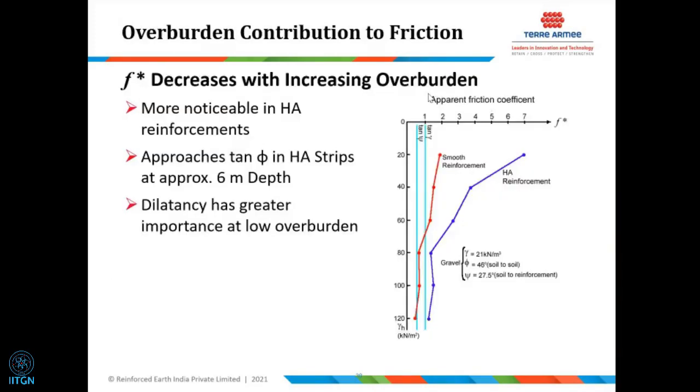And generally, the coefficient of friction depends on different kinds of soils. With a high coefficient of uniformity soil, with more gravels, you can get a much higher coefficient of friction. And with a silty sand kind of soil with coefficient of uniformity within 2, you get a certain kind of coefficient. But it is well proven that this behavior is more or less the same. The exact value of coefficient may vary, and there are several tests that have been done, not only abroad, in India, and there are a lot of papers available.